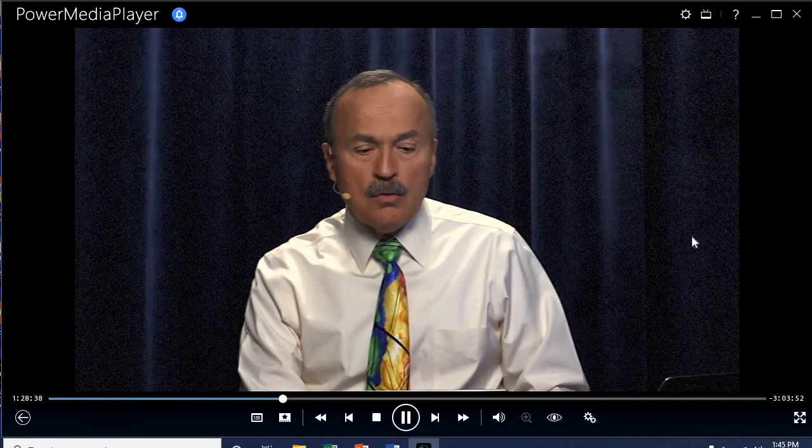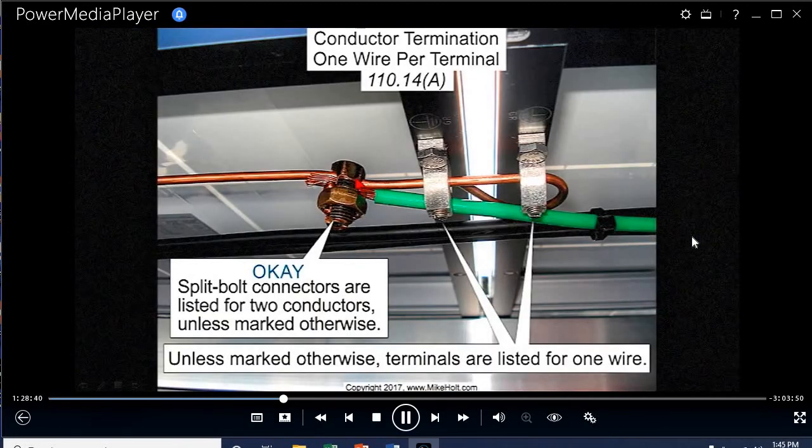If Don is correct, that a split bolt connector cannot be used with a conductor 6 gauge and larger, I hate that word larger, then that is probably a very common split bolt connection made in the solar industry. Because they usually use 6 gauge wire, solid, for the bonding of their modules on their arrays. Don't see anything wrong with it. So, Brian, let's just double check that.